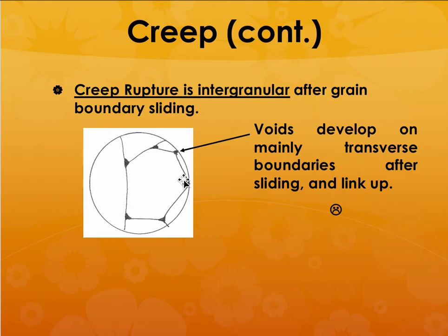So that's the same thing that happens here in this kind of a material. It just creates these kinds of cracks, and then the grains will start separating out from each other, and then they will start sliding against each other. At elevated temperatures, especially beyond half the melting point in degrees Kelvin, the grains will have a tendency to slide over each other. When they slide over each other, those voids will start becoming big and start linking up. So that is what is happening.